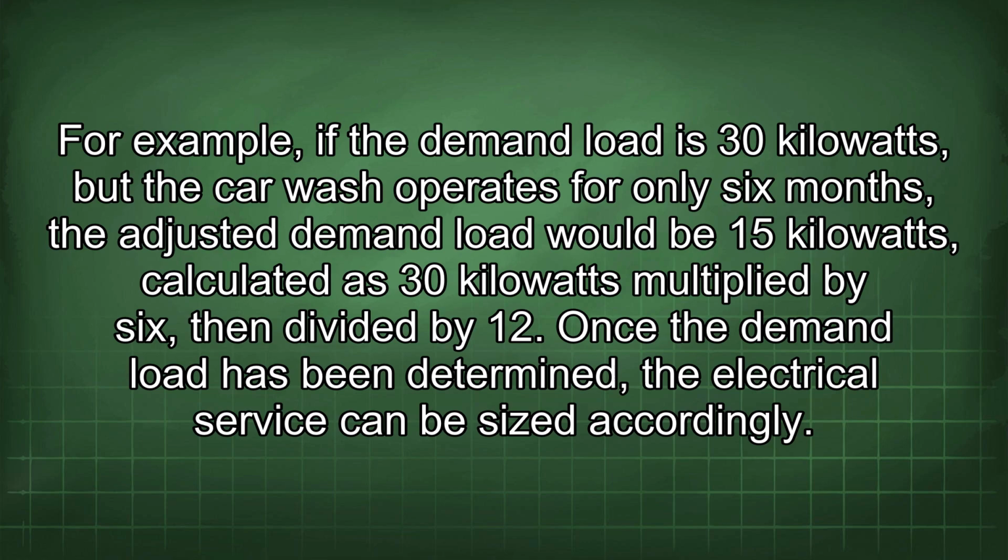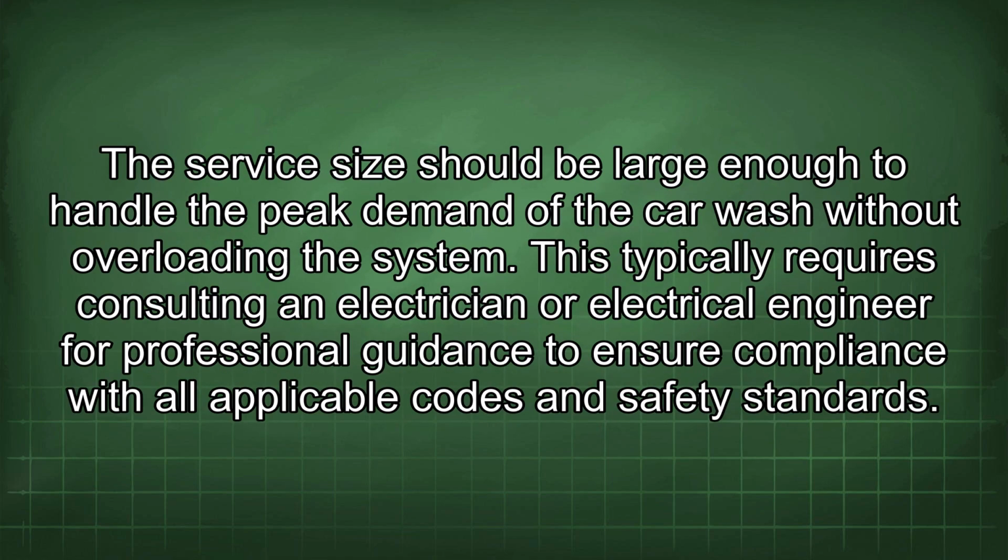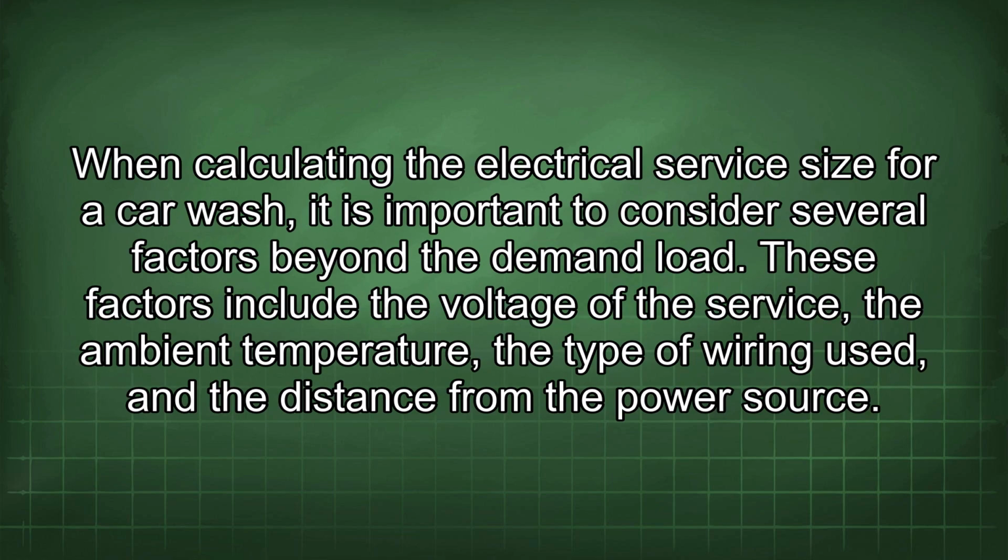Once the demand load has been determined, the electrical service can be sized accordingly. The service size should be large enough to handle the peak demand of the car wash without overloading the system. This typically requires consulting an electrician or electrical engineer for professional guidance to ensure compliance with all applicable codes and safety standards. When calculating the electrical service size for a car wash, it is important to consider several factors beyond the demand load. These factors include the voltage of the service, the ambient temperature, the type of wiring used, and the distance from the power source.